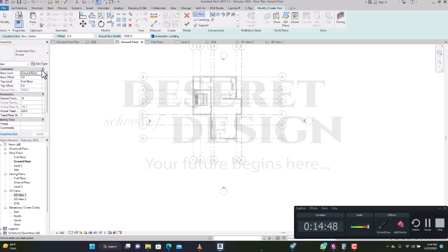You need to draw your stair. It has to go from level to level. So it has detected the base and it has also detected the first floor. So you don't need to set the height. So you will see that in the desired stair height, it is grayed out. Do you get it? Yes. It means that per where your ground floor is and where your first floor is, it has detected that height already. Yes.